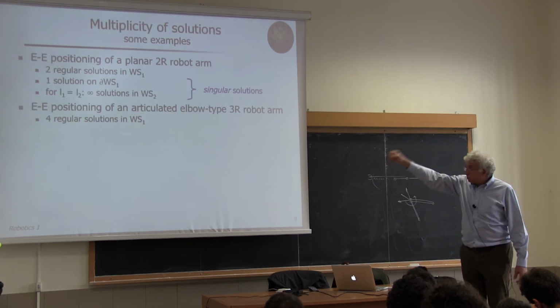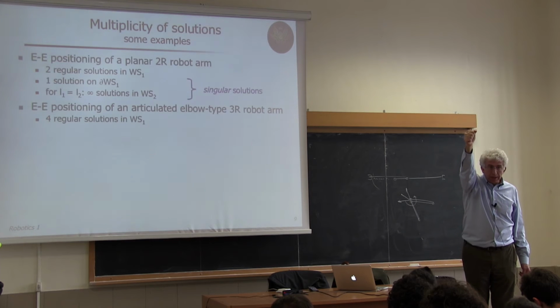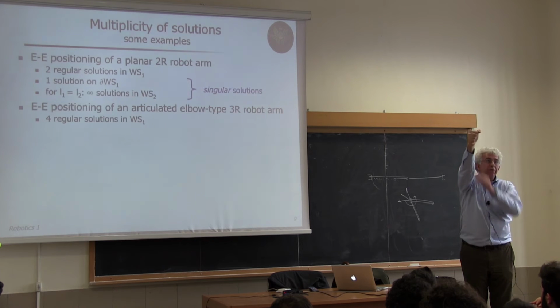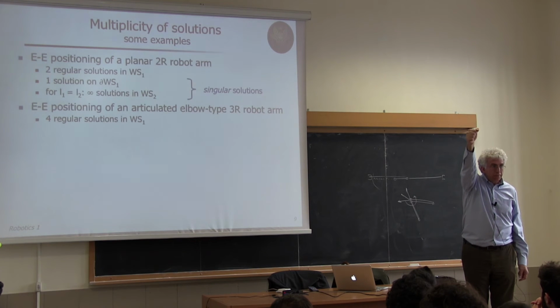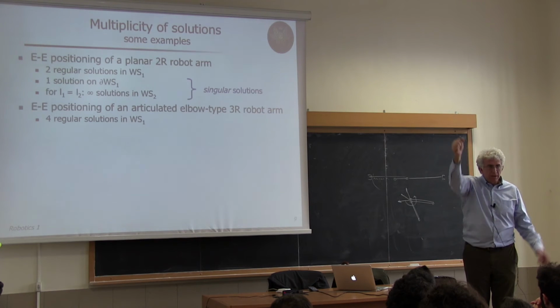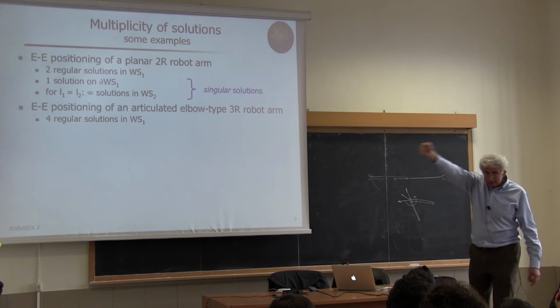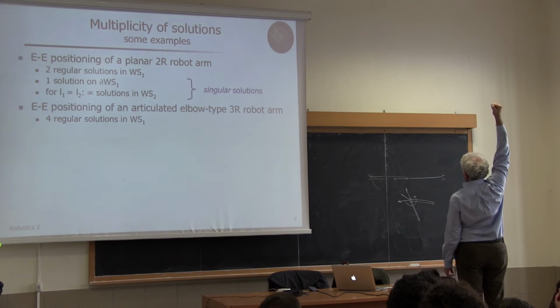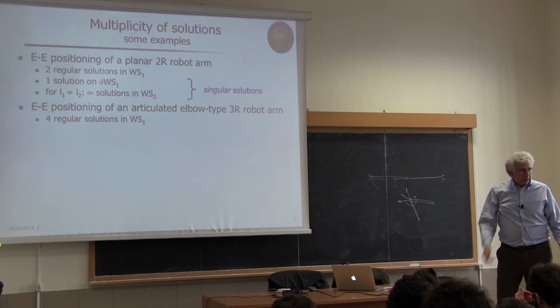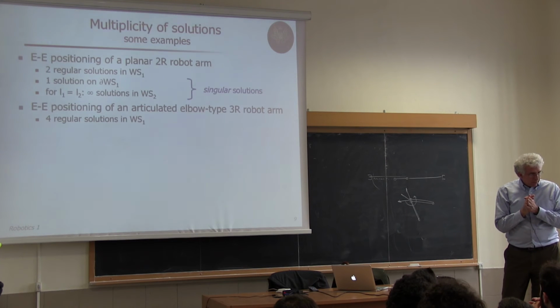for just positioning, and I have three joints like for the Unimation Puma, how many inverse kinematic solutions are there? When I need to stretch my arm and forearm. One or two? I've heard both. In general, two, because I have this solution and then rotate and extend, and I have the other solution. It's just the elbow down, elbow up that collapse into one. Okay?